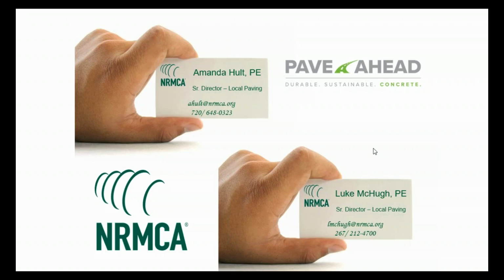So we just have to understand that if we are going to use lightweight aggregates and utilize that internal curing, there might be some considerations that we have to think about. But as a field mechanism for increased curing, lightweight aggregates and internal curing are great. It's just a matter of being able to find them in your area, and I think there are enough suppliers across the country to where they are fairly easy to find.